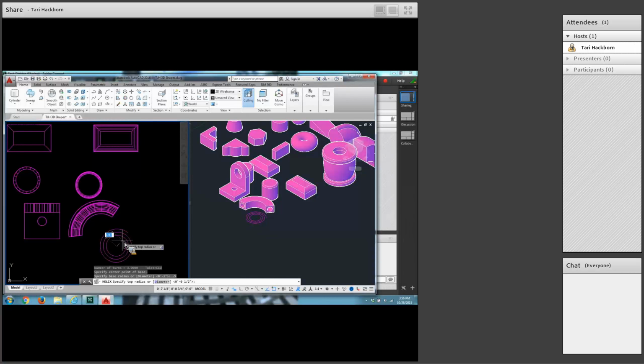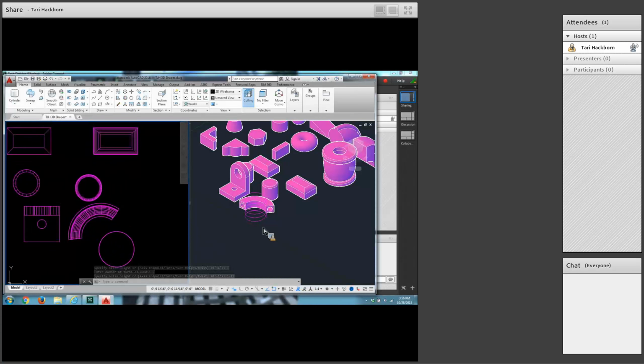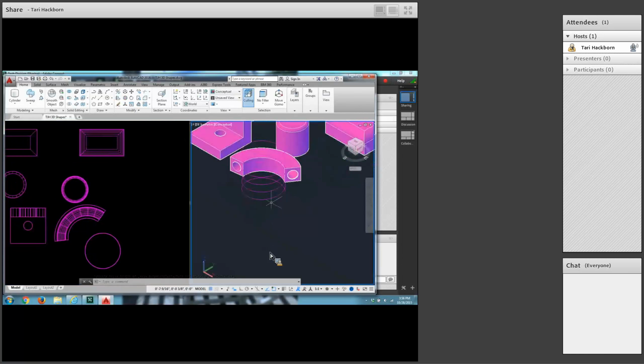And then just do another enter. So you'll have a ½ inch radius at the top. Then click on turns right here and type 6 and enter. And the height, you can see it pulling upward on the other side, is 1.25. And enter. And your helix is done. It just looks like a circle over here. But over on this side, I'd like to move it away from that thing a little bit, just so we can see what's going on. Let's move it out just a smidge.